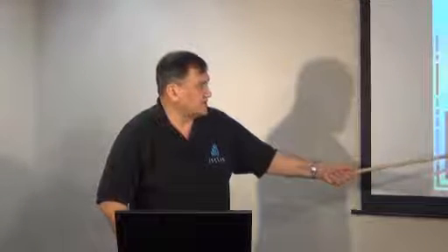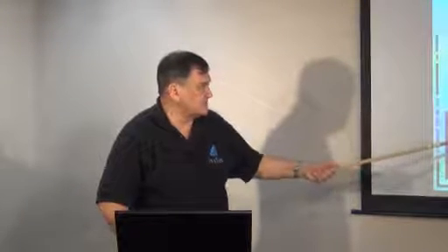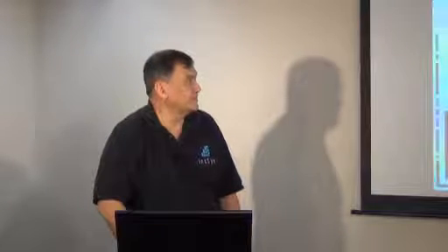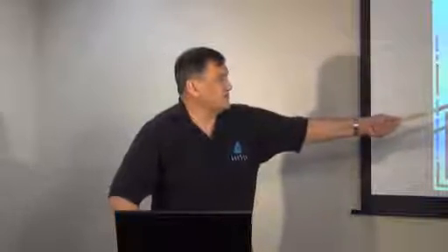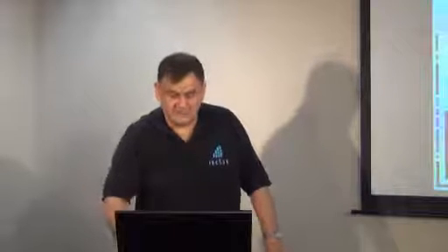If we come in on this line, we close the tie breaker here, the middle breaker, then we'll energize this line, and then we close this one to heat up the bus, and then we connect the other line that we want to go out through on a path. That dependency is there. We have generator capability curves, and we have accurate discrete tap configuration. So the models are much more accurate and they're real time.